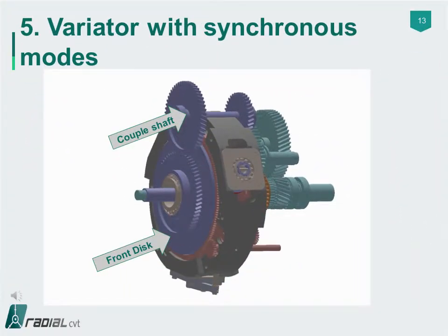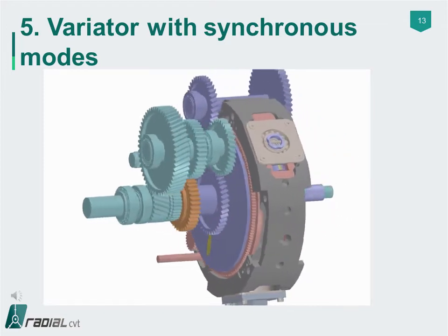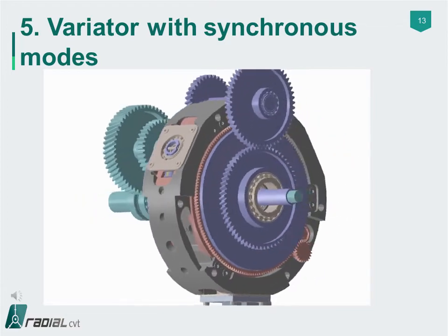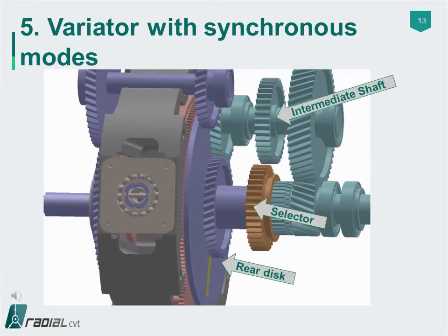In transmission applications in the automotive industry, in hybrid and pure ICE applications, the current norm is a ratio range of between 9 and 10, which is currently implemented via 9 to 10 speed automatic and dual clutch transmissions. The radial CVT configuration has practical limits, which limit the ratio range to around 4.5 to 5. Therefore, to meet the above ratio range, a multi-mode synchronous system is required.